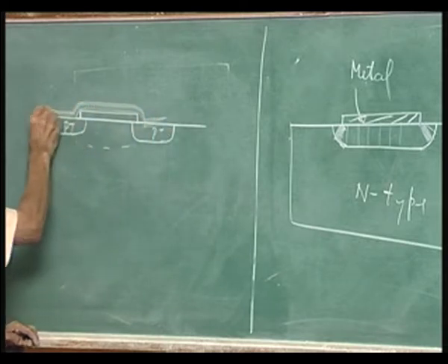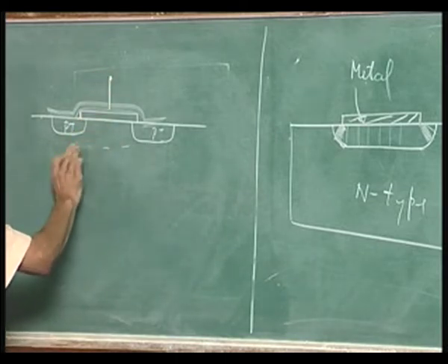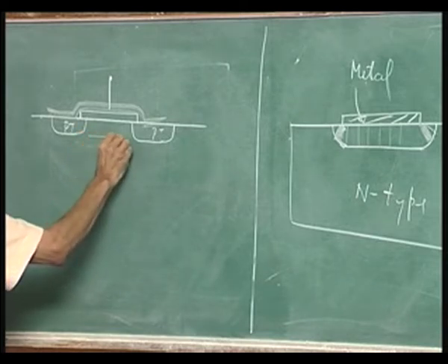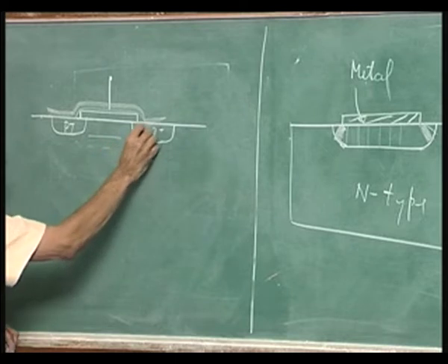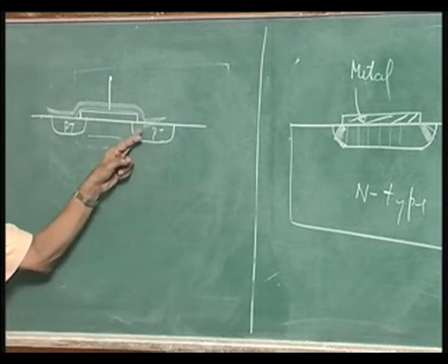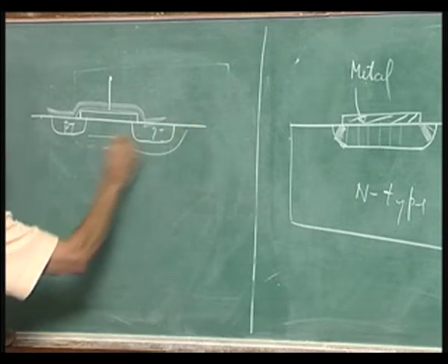If you see the diagram, both are shorted together. So, when I apply voltage here, the depletion layer formed here, in the absence of this, it would have crowded down like this, there would have been a crowding effect. Now, there is no crowding effect in this portion, the depletion layer moves like that.